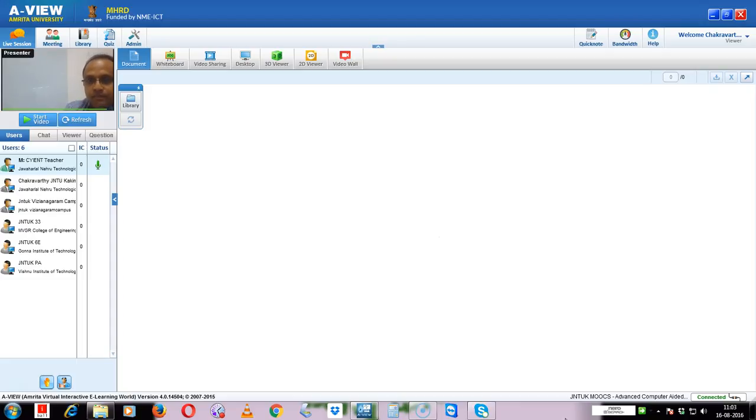If you see here, for example, this is a hollow plate, very thin. Here we can model this as an area component with a hole, and we can assign the thickness. So this is a plane stress problem. I hope everybody is able to see my screen. If you have any issues, you can mention them in the chat.